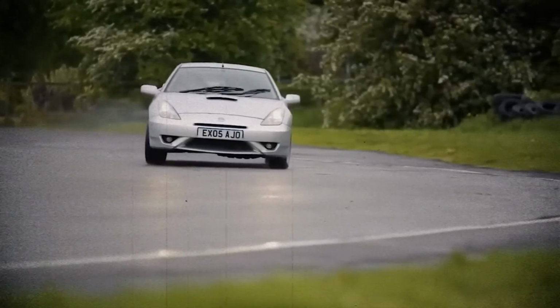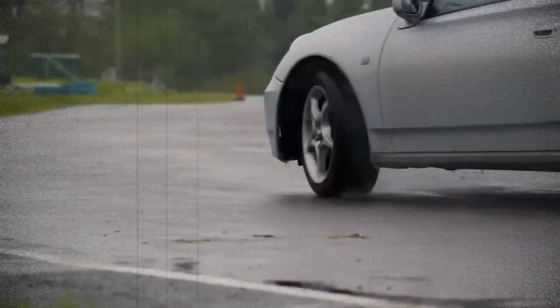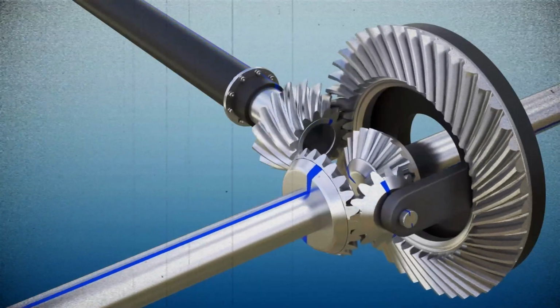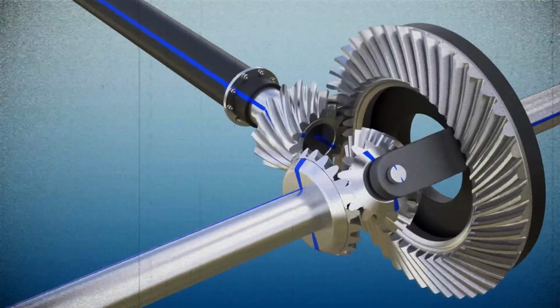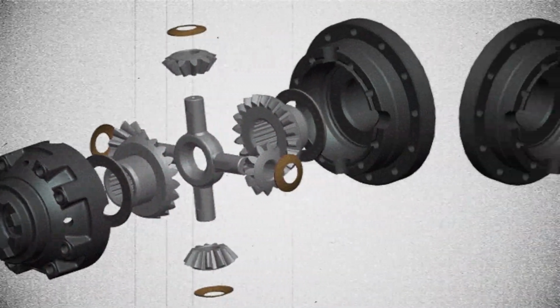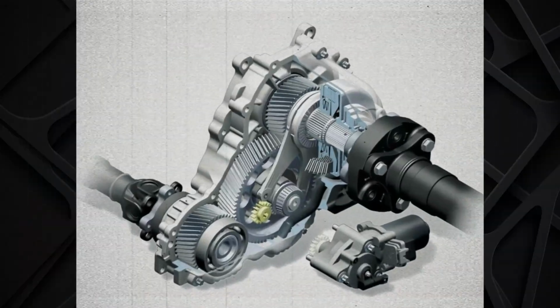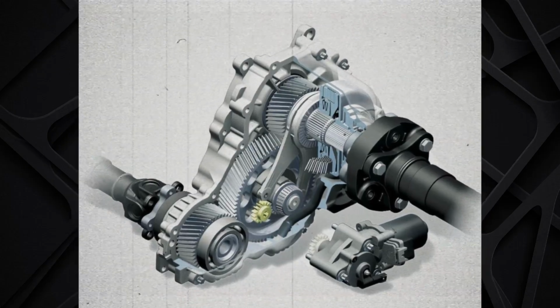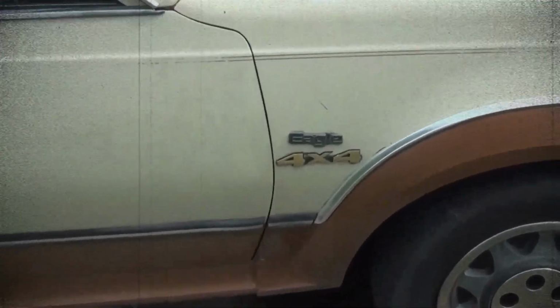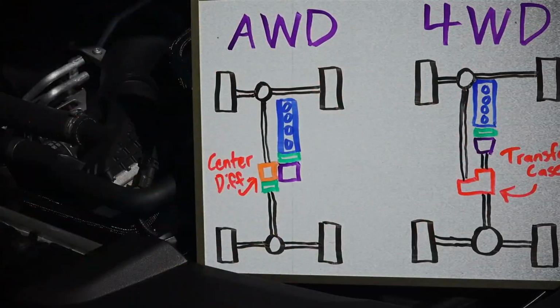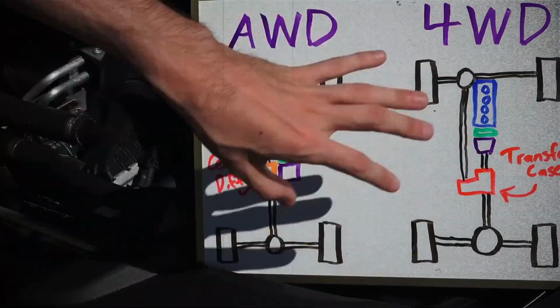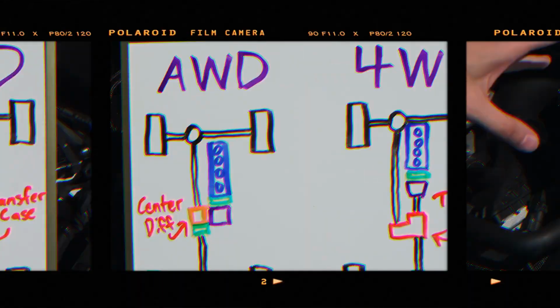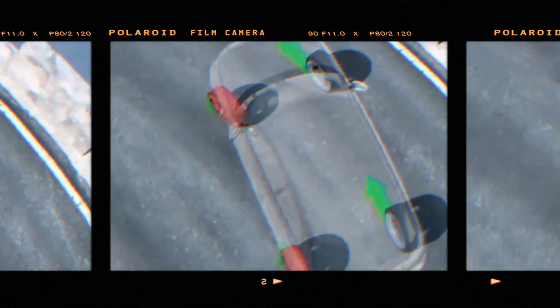Like gear reducers, differentials can be installed in various locations depending on the vehicle's drivetrain. Front-wheel drive: the differential is integrated into the gearbox housing. Rear-wheel drive: the mechanism is located in the drive axle housing, often referred to as a reducer. All-wheel drive: the differential can be found either in the housing of one of the axles or in the transfer case. If the differential is absent or completely fails, the vehicle loses maneuverability.